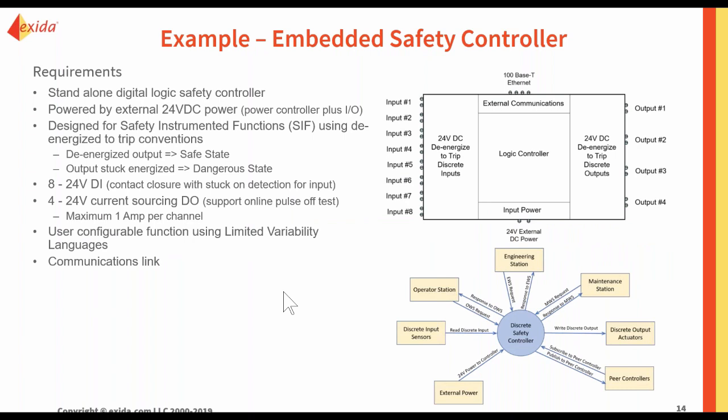For example, imagine our marketing department wants us to build an embedded safety controller. And they say, fine, we want a standalone digital logic safety controller powered by external 24-volt DC power, which is available for both the controller and the I/O devices. It's designed for safety instrumented functions using de-energize to trip conventions. In other words, de-energize is the defined safe state.